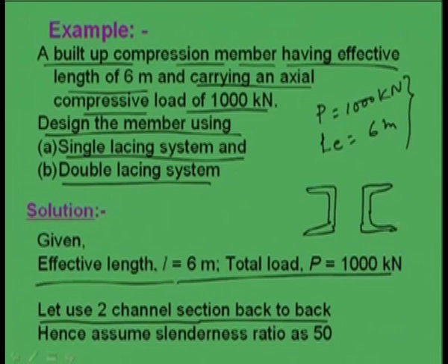Okay. Now, from this what we have to do? Now, we have to find out the spacing through which the applied load can be carried without any problem, and second is whether it will be back to back or front to front. Now, generally back to back channel is preferable from the designer point of view. From the maintenance point of view, we have shown earlier why channel section back to back is preferable.